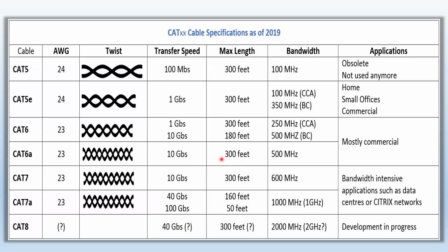To someone who has spent over 30 years in this business, it is a huge game changer, because every installation would hover around 300 feet, everything would be with the 300 feet in mind. Actually, it's 328 feet, but you don't want to install 328 feet end to end, because you still have to use patch cords to connect from the jack or outlet to the PC or whatever other device.